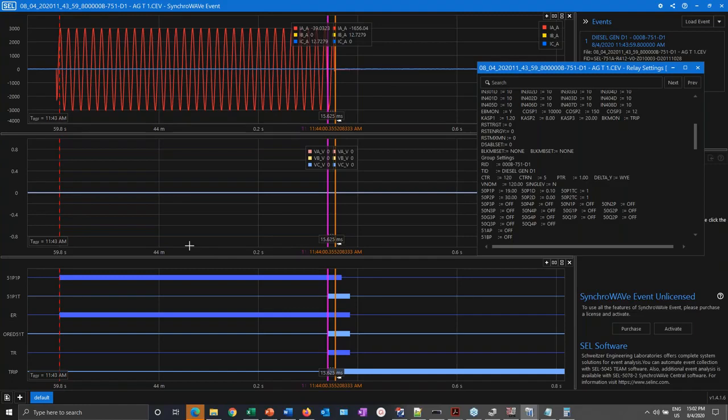You have to realize that there are differences between the time that the commands are issued and the time the digital signals appear inside the relay, and then you have 4 milliseconds, depending on the type of relay, of processing time, and then you have the test set, which also doesn't behave absolutely instantaneously.